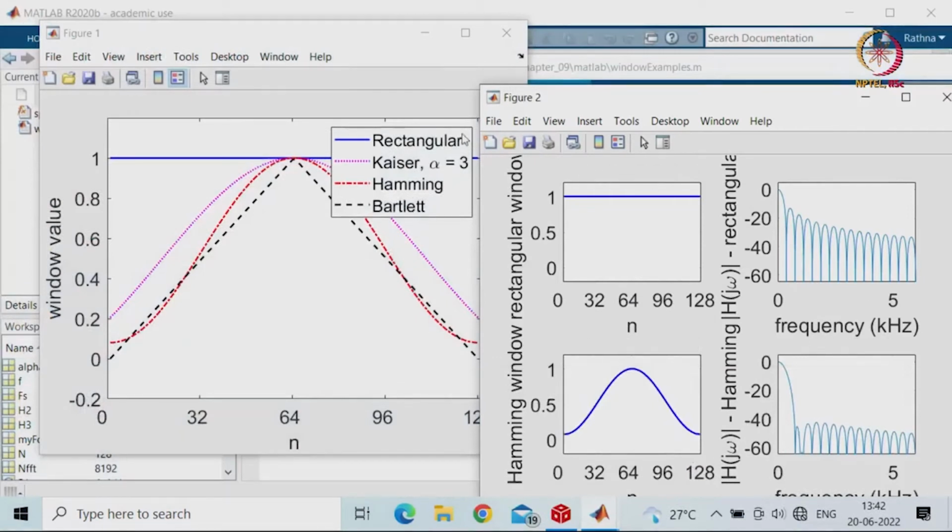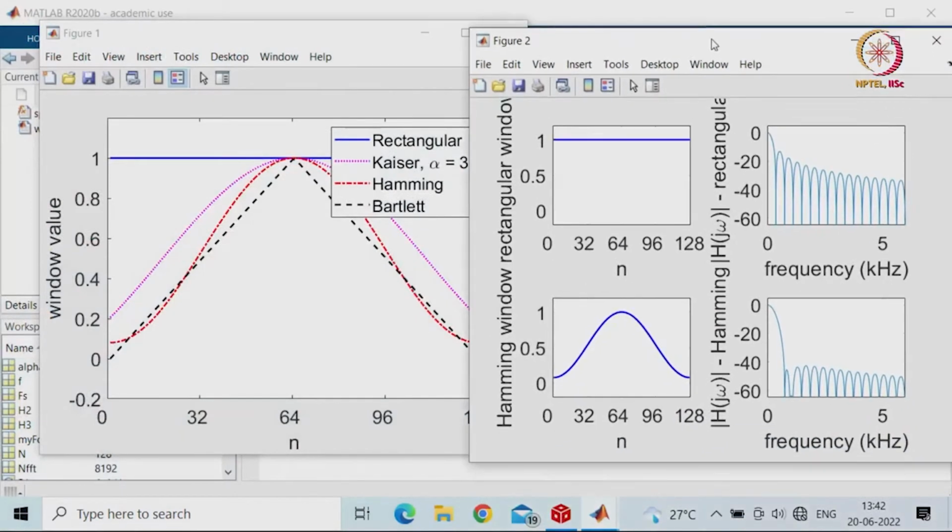In this you have passed the data through the rectangular window, and you see the frequency response after passing through the rectangular window, and then using the Hamming window. So, how the output is represented: this is our main lobe, this is basically a low pass filter, and these are the side lobes.